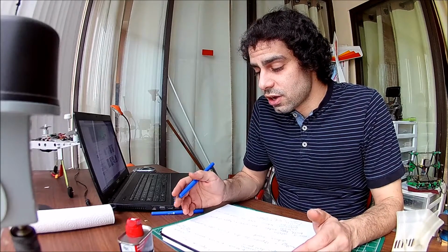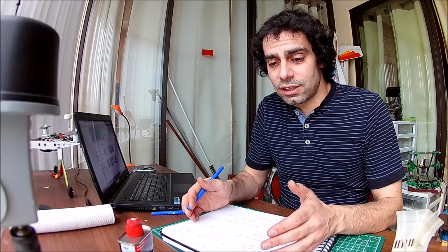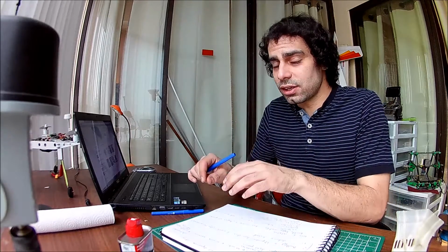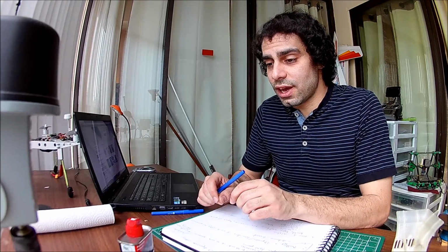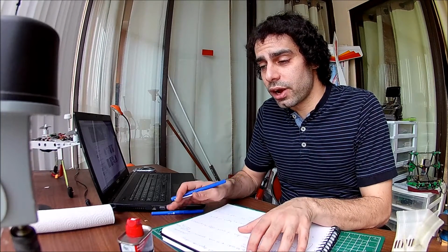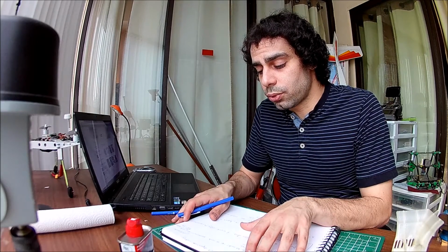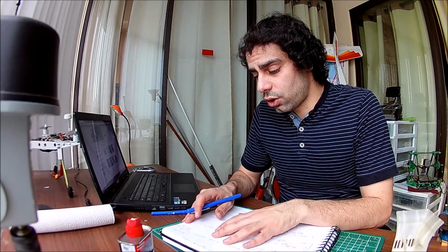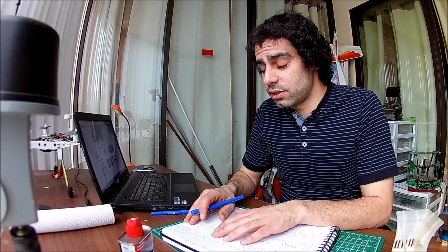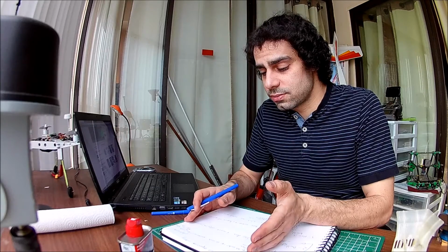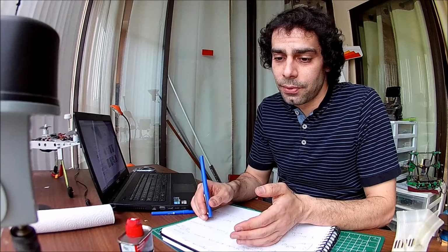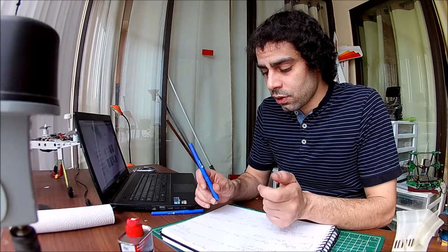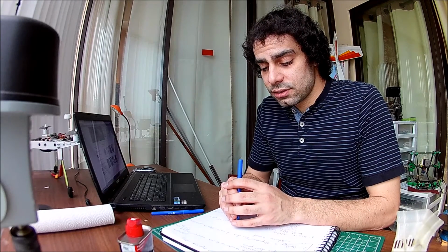On some 3D printers, the G-code implementation system is standalone, as in the 3D printer is not directly connected to a computer. It works via SD cards, where you transfer the files via SD card. Other 3D printers are directly connected to your computer, and the G-code processor or interpreter is also the implementer as well. There are advantages and disadvantages to both systems. Typically, standalone systems tend to be more reliable, but they're less dynamic. So let's go for a quick overview of this process and see how it goes.